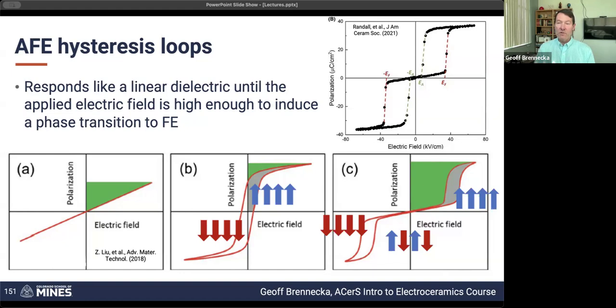Because if you want to use a capacitor in some sort of device, let's say that device is operating at a megahertz, then you've already hit 1 million cycles after just 1 second. So fatigue lifetime matters. For capacitors and similar electronic components, we need cycle lives of 10 to the 9th, 10 to the 10th, sometimes 10 to the 12th cycles.